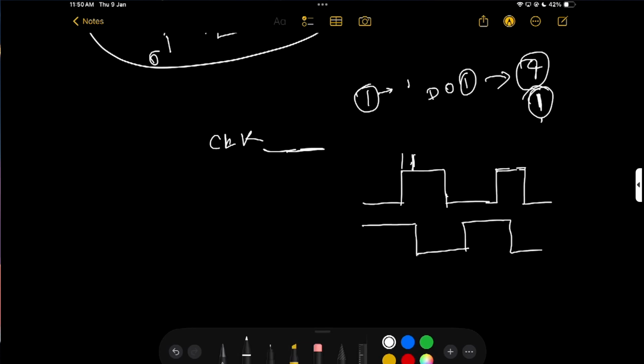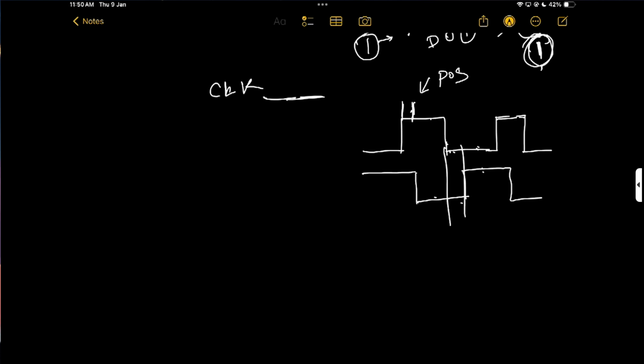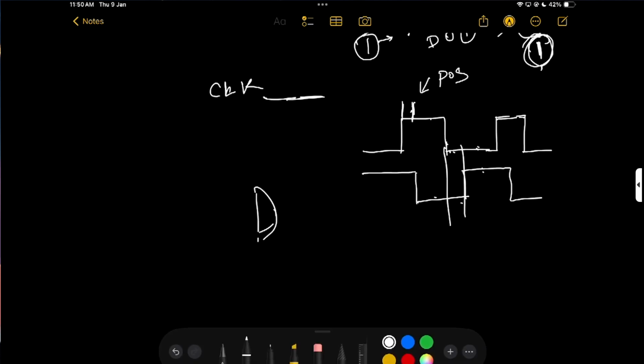So just like that, in here for a small period of time the circuit should be on. This is my positive edge triggering and how the circuit looks. If both are 1, at that time only the output will be 1, otherwise the circuit output will be 0. So 1 0, 0 1, 0 0, both 0, then 0. Okay, so the circuit is nothing but you take an AND gate.